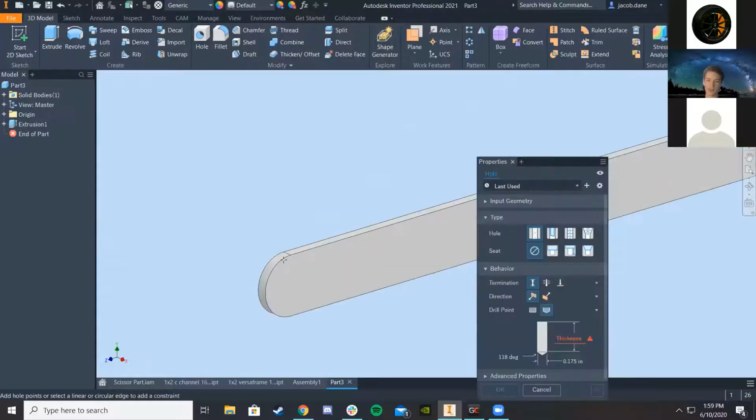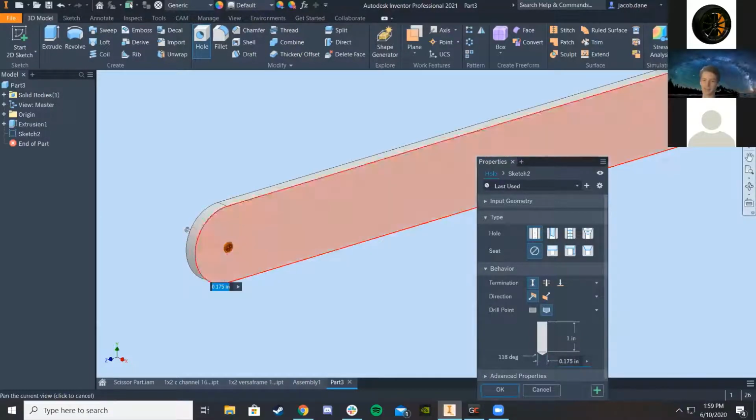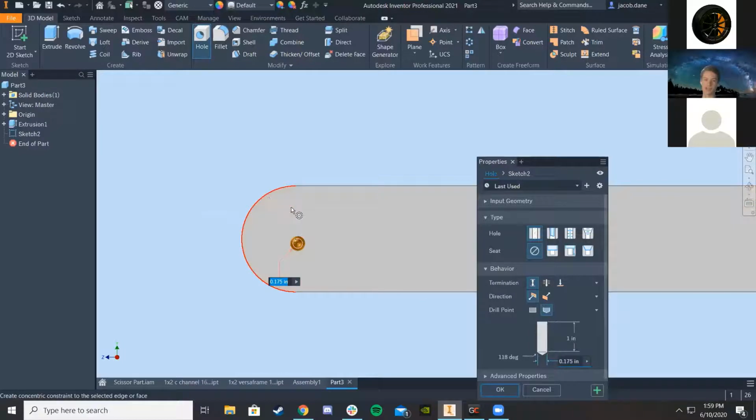I'm gonna make the holes that we need for that. And so I already know right now the kinds of things we're gonna use. And so if you're questioning, it's just because I already know. But so what I'm gonna have between there, you could have just a bolt that you can use to actuate that mechanism. But because we might be having a lot of load on this, I'm actually going to use something called bushings, and those help movement and reduce friction between the metal pieces whenever you're having a lot of load and you're trying to actuate any parts. So I will show you that later, but for now, that's just why these holes can be super big.